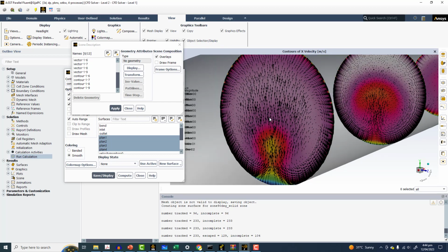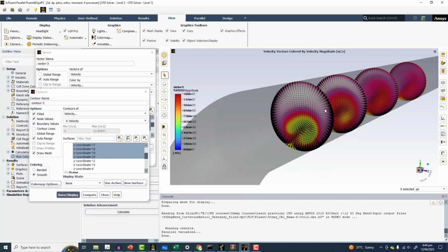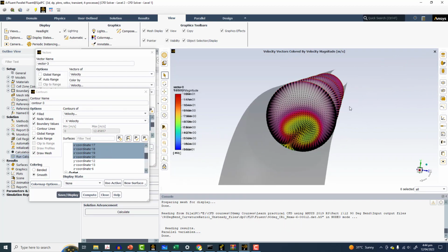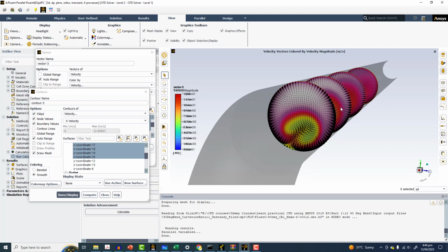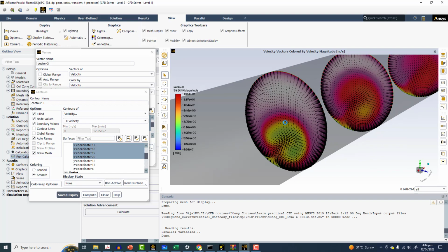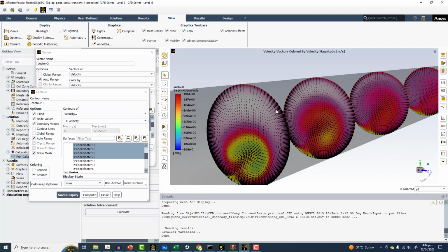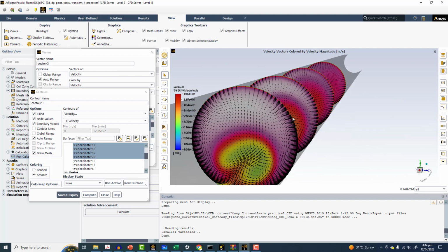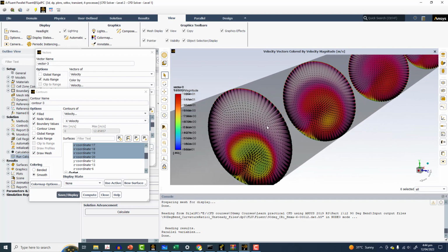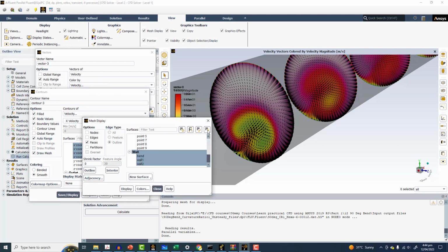So that's why this case is stated as steady state, but with the curvature ratio equal to 1, which is less than 1.5, the vortex is fluctuating in time and it is changing position in space and time at the same time. So you can see the flow like this. Okay, and if I display the path lines, you will see this more noticeably.